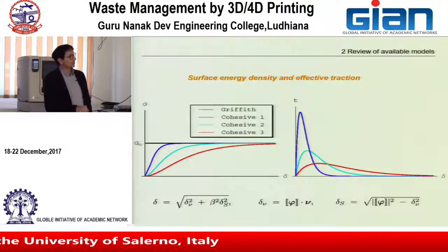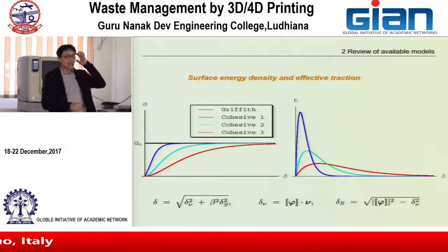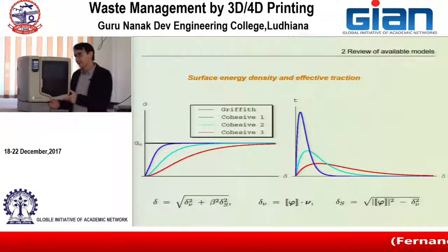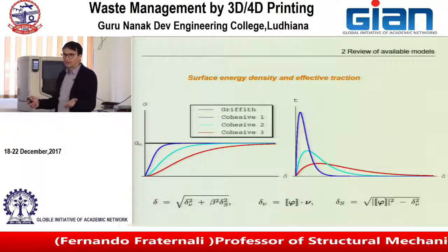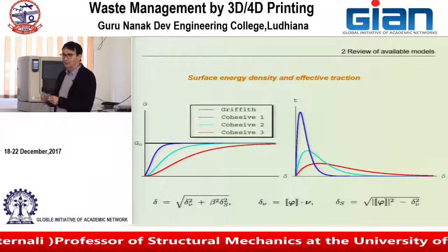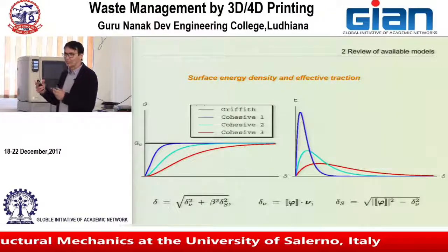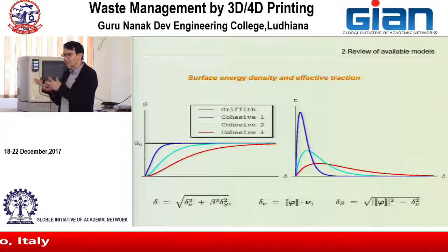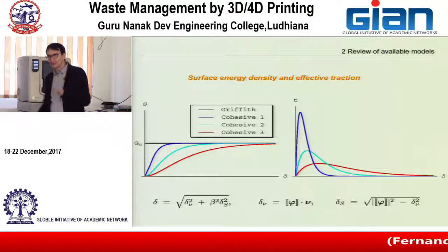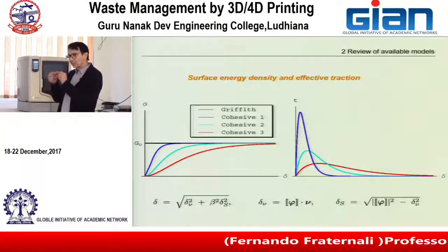This function can have different shapes, and you can have a different fracture model, which is called cohesive fracture. In cohesive fracture, the surface energy density depends on the crack opening displacement, because you can imagine that there are some bonds.